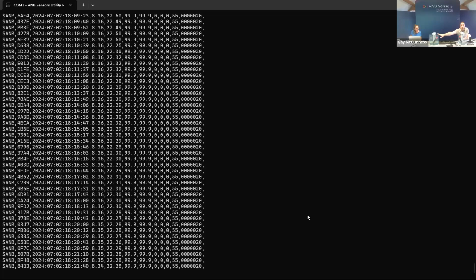Can we share that one? Yeah. So in this setup here, we have a freshwater tank and a high salinity tank, and we're monitoring these continually as we're going along. This is coming from our ocean, high salinity tank. Now our salinity sensor will only work up to 7 ppt, and that's why you won't see any salinity or conductivity outputs here.